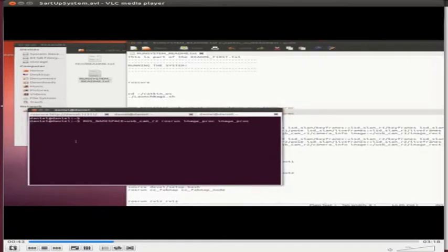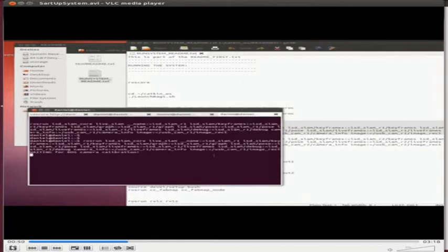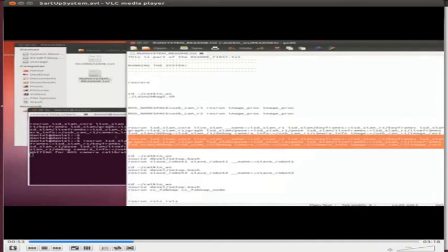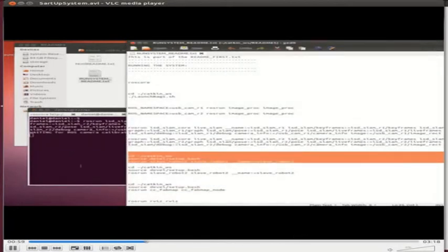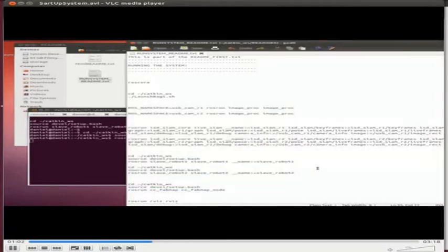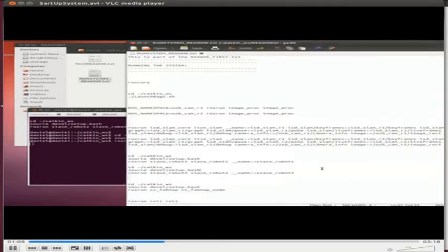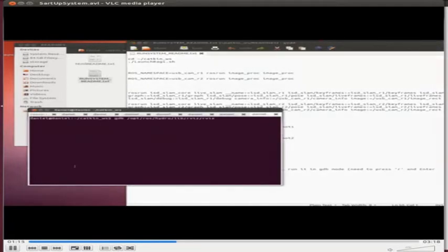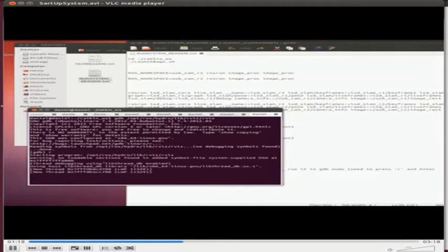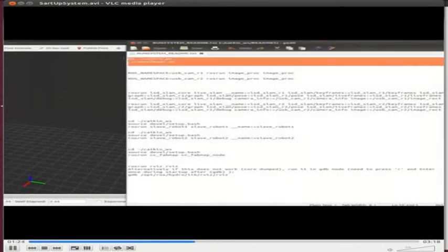This is like the rectification for the images of both slave robots, the SLAM algorithm on both robots, then the processing of the data, that means the filtering of the estimated data on the slave robots, on robot 1 and 2, and RViz in order to visualize the estimated data, the local maps and the global maps on the central computer.